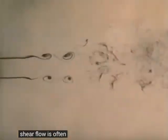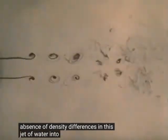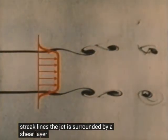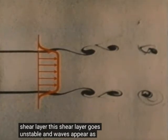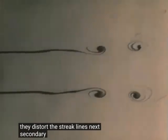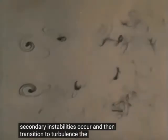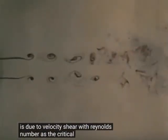A shear flow is often unstable, even in the absence of density differences. In this jet of water into water, shown by dye streak lines, the jet is surrounded by a shear layer. This shear layer goes unstable and waves appear. As they grow, they distort the streak lines. Next, secondary instabilities occur and then transition to turbulence. The instability is due to velocity shear, with Reynolds number as the critical parameter.